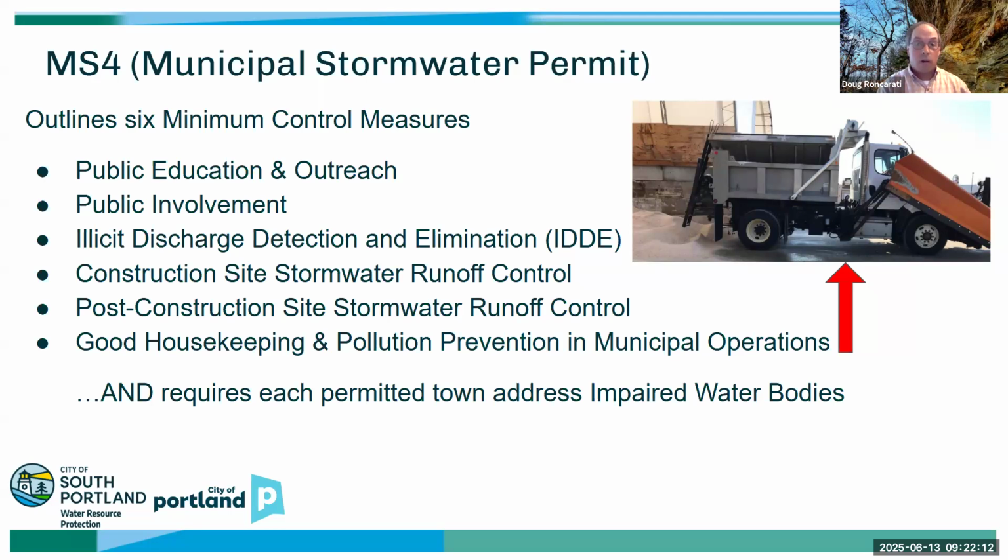Post-construction stormwater runoff control involves encouraging, incentivizing, and requiring public and private property during development and redevelopment to install stormwater management controls. That will help deal with some of the existing problems that we have with stormwater runoff, but also new development where you're going to greenfield sites. It helps to reduce the volume and the pollutant level coming off of those sites.